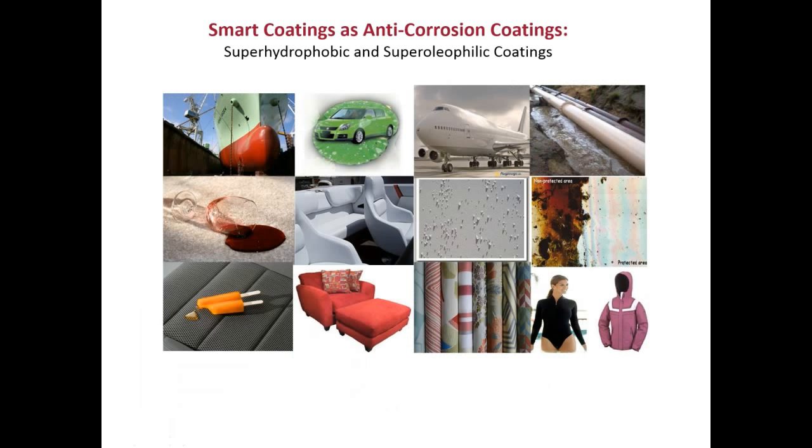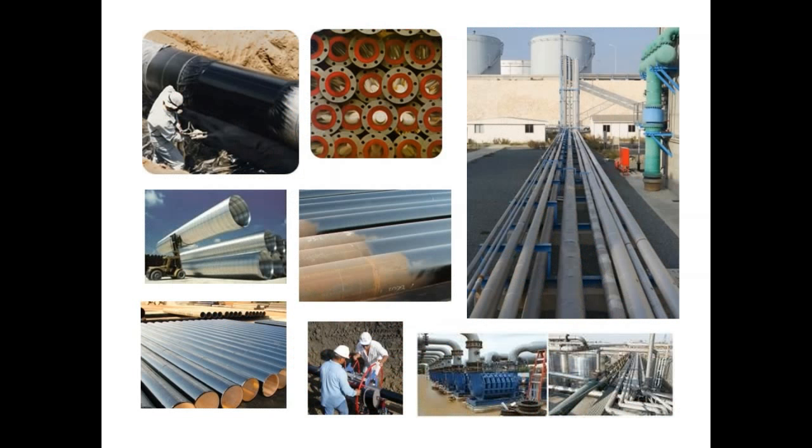Here, we have to then go to another route to protect corroding metal parts by going to coatings or smart coatings. Smart coatings can be used in many ways, not only for preventing corrosion, but preventing wetting, staining, thermal stability, etc. So smart coatings means smart paint. And smart paint means that you need to look at the application of paint, whether it's spraying or thermal spraying or powder coating, etc., on different structures.